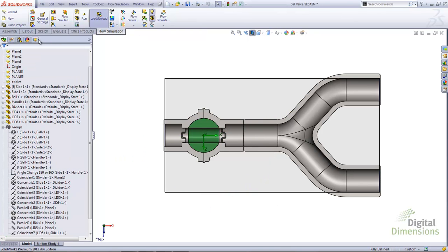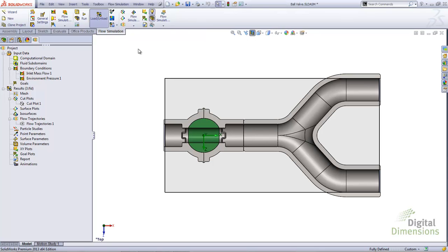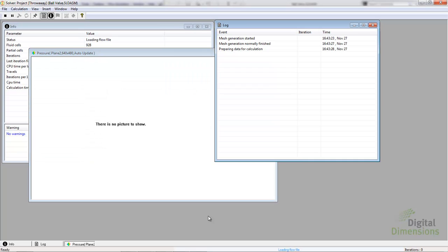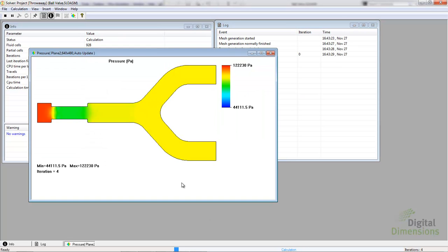Because we're fully integrated within SolidWorks, there is no need to go in and recreate the setup or import and export any geometry. All that is needed is to go in and rerun your flow study. Now again, if your preview results look incorrect, this would be the ideal time to stop your study, reassess your initial setup or assumptions, and then return to running your study.